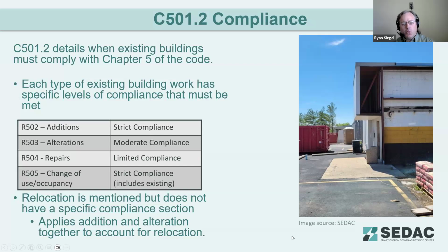Alterations, we're deeming here as moderate compliance. What that deals with is whatever your alteration is covering, that needs to be brought to the current standard, with a few provisions and allowances for that. So we're calling out moderate compliance. And then repairs oftentimes do not have any direct compliance other than to return it back to the way it was before the damage occurred. So we're calling that here limited compliance.